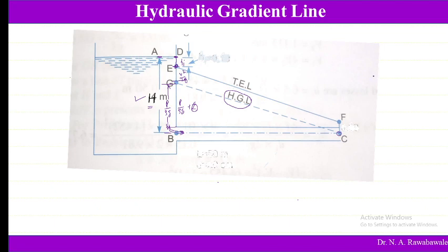As we know, HF is equal to 4 F L V square divided by 2 G D. The 4F and V square by 2GD for a given pipe remain the same, whereas as the fluid flows, the length L is going to increase, and because of that this HF is going to increase. So as HF increases, that is subtracted from this total head, and finally we get the total head minus the maximum friction loss. Then we get this point, and we draw one line. That line is known as the total energy line.